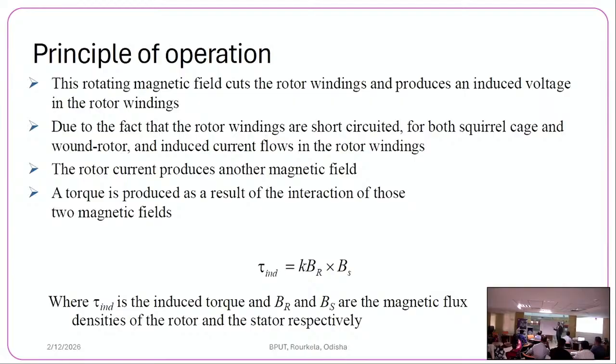So it depends upon that. So the rotor induced EMF, at any speed, has magnitude s times E0 and frequency s times f, and the rotor carries this current.